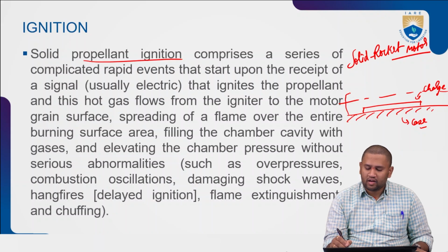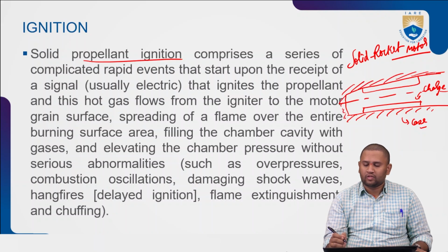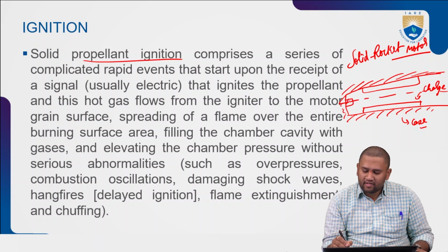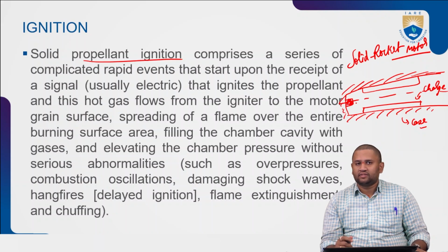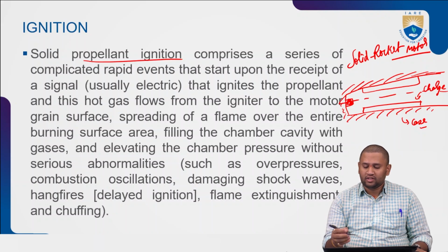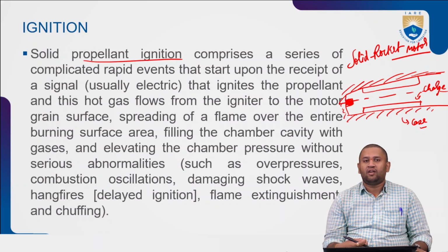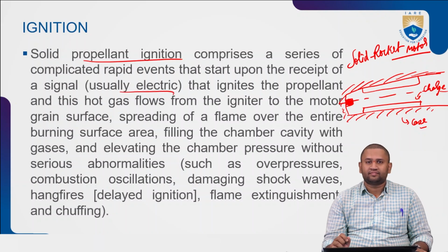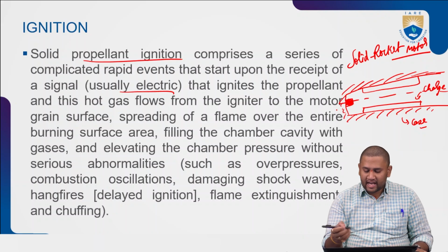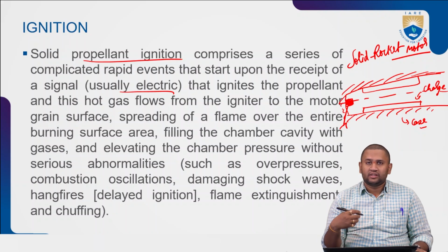Now, at the end of the casing, we'll have a small pyrotechnic charge, nothing but a small explosive packet. When we want to start my solid rocket motor, this pyrotechnic charge gets signaled by electricity, because electricity travels at a much faster rate than any other signal, so as soon as it gets the electric signal to start the engine,